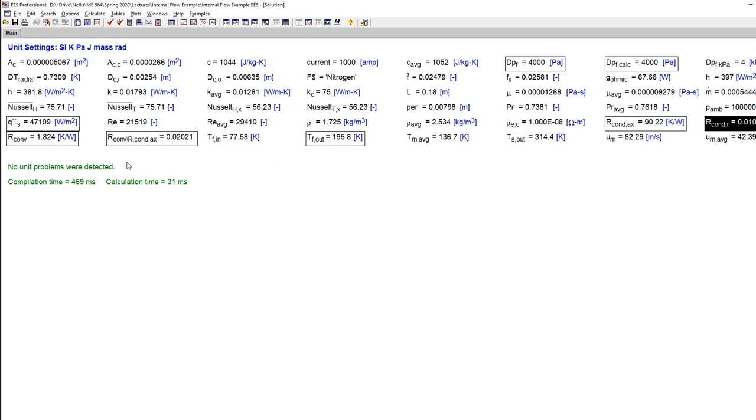So, if I'm a piece of energy, my best, easiest path is to go straight out and be convected to the fluid. I'm really not going to be that interested in going up or down. That's not an easy path for me to take. So that is the limit where I basically have a constant heat flux.